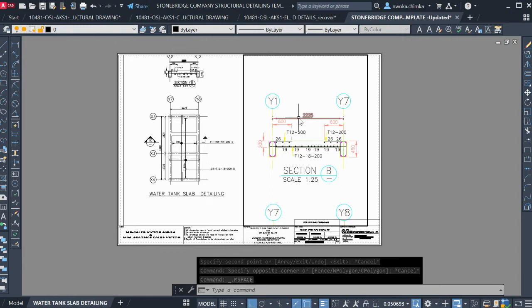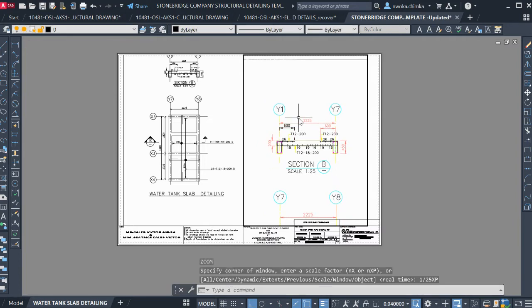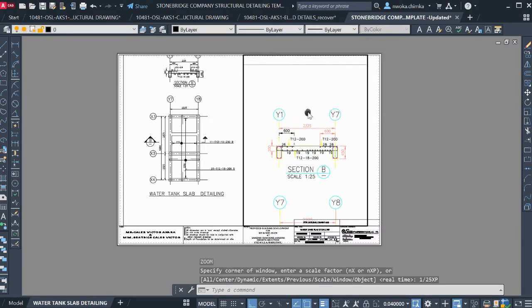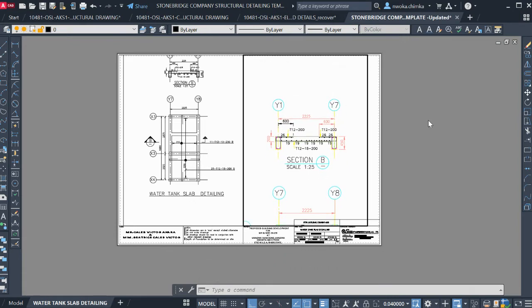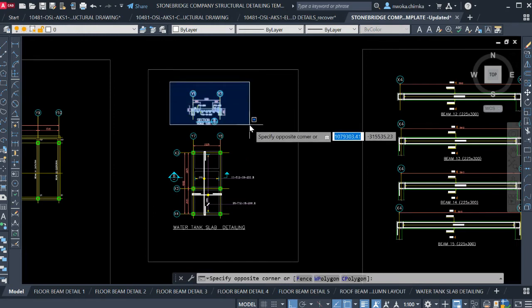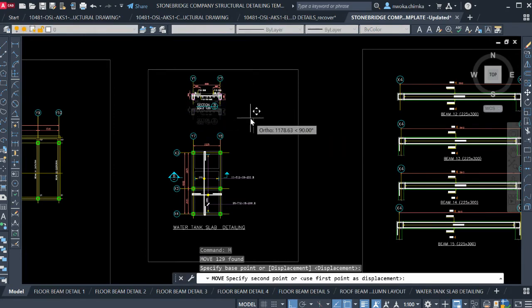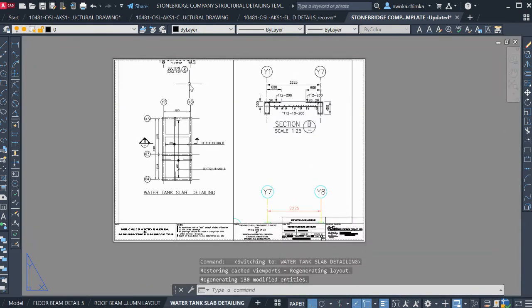So I'll use a scale of 1 to 25. So Z enter 1 all over 25 SP. Let's see how that looks. This is okay. So 25 is okay. So I can just pan this downward right now. Pan this or just keep this here first. Press on this place and then come back here. Move this one out from this place entirely and just take it upwards, so it will not show again at the same place. Okay, it's trying to show here.